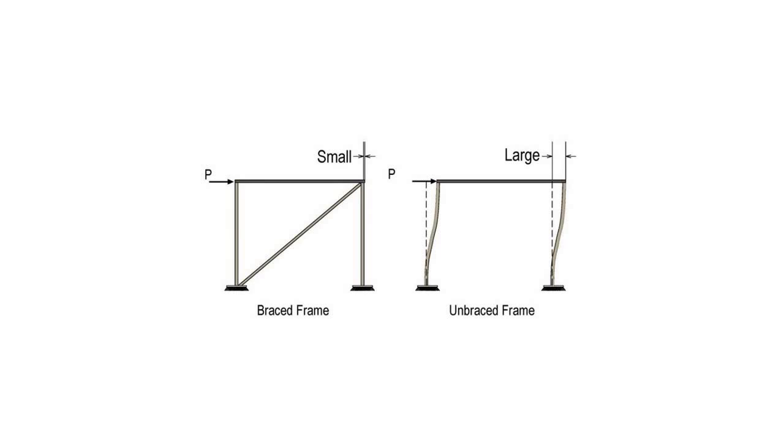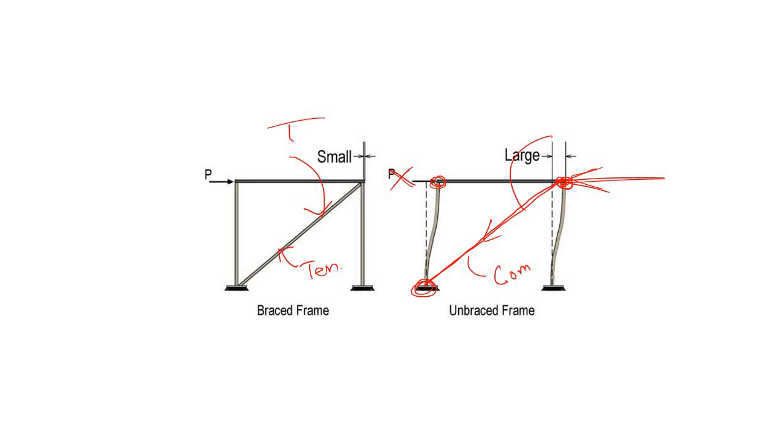Yes, so let's say you are applying a lateral load like this, and in this case all these joints are pin joints, there is no lateral load on this side, and you provide a bracing like this. It will directly transfer to the foundation through this bracing. Now this bracing is under the action of compressive load, and initially it was under tensile load. So basically you can design a bracing for two types of load. First one is tensile load, second one is compressive load.